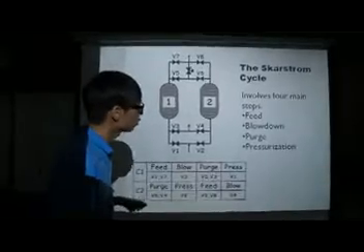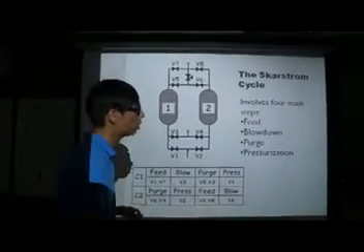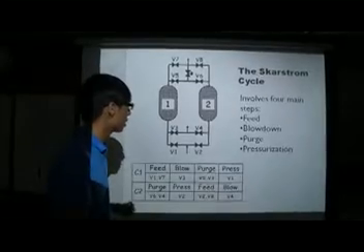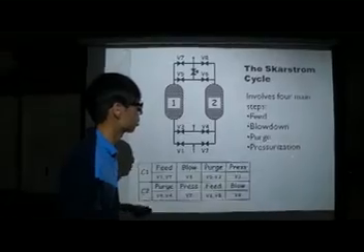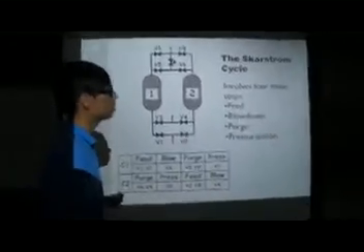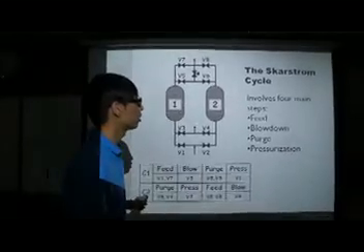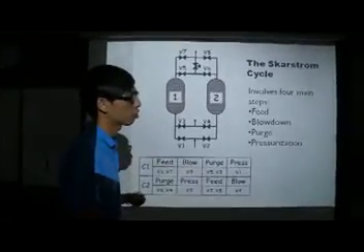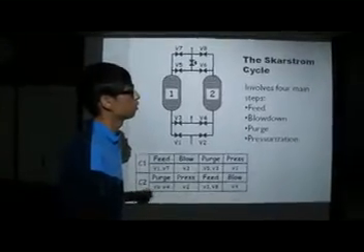The next one is the pressurization step. The pressurization step is where you prepare the adsorption column for the next feed processing. It is easily achieved by redirecting highly pressurized air or nitrogen into the column until the column achieves the required pressure.